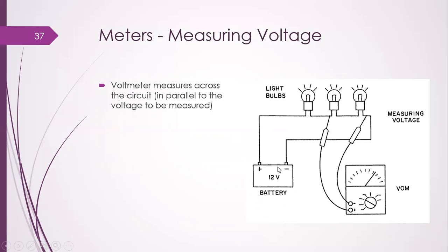It is not mandatory to connect these load bulbs in series; another way of combination can be arranged in other ways. If we need to measure the voltage in an electronic circuit, then we need to connect the meter in parallel with the load.